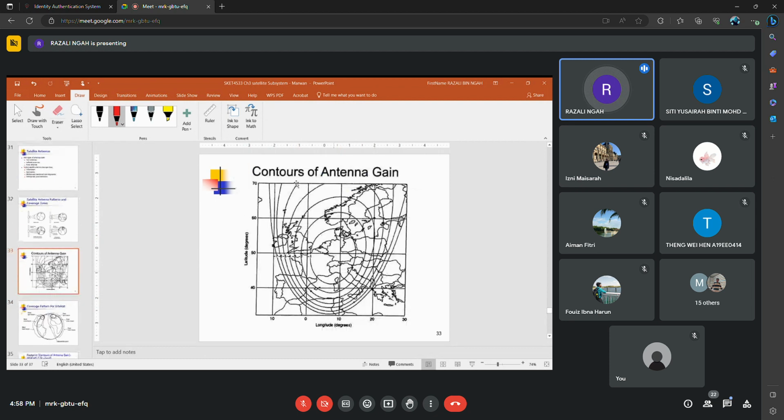This is the one I mentioned in the link budget that depends on the contour, or footprint. If our earth station is located in the center, there is no off-axis loss, because both antennas, on the satellite and the earth station, are inline.